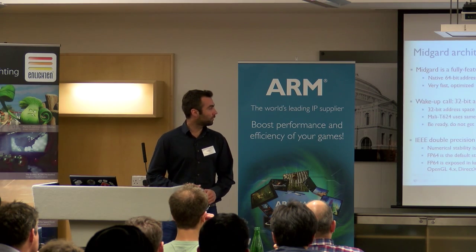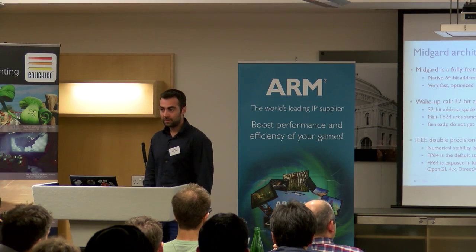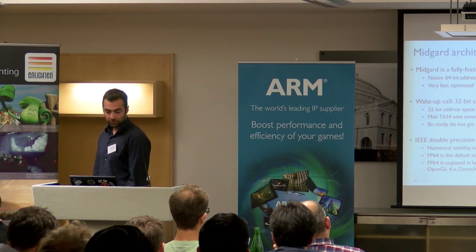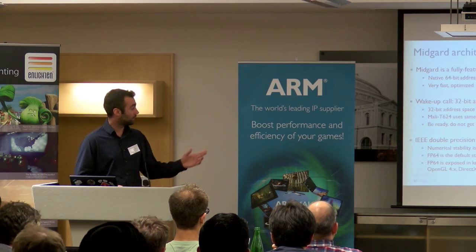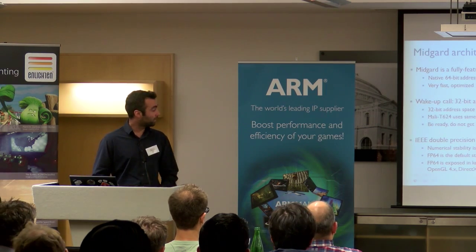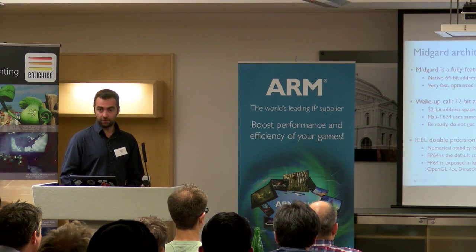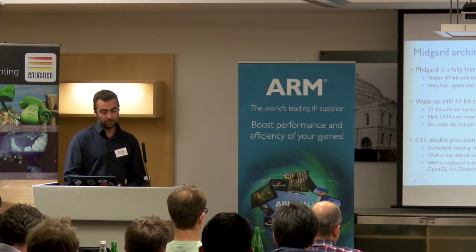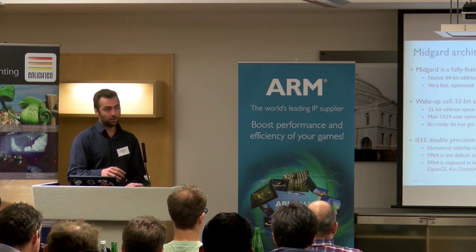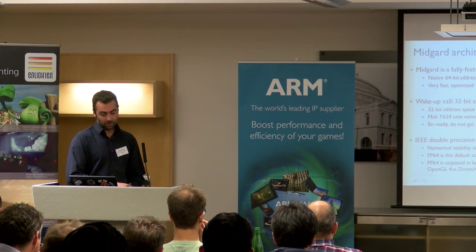So Midgard GPUs are offering both 64-bit address space as well as 64-bit compute processing, and this is also very important for OpenCL, because full profile OpenCL does require 64-bit precision, and by supporting that, you can easily take the desktop compute applications and port them to your mobile device.